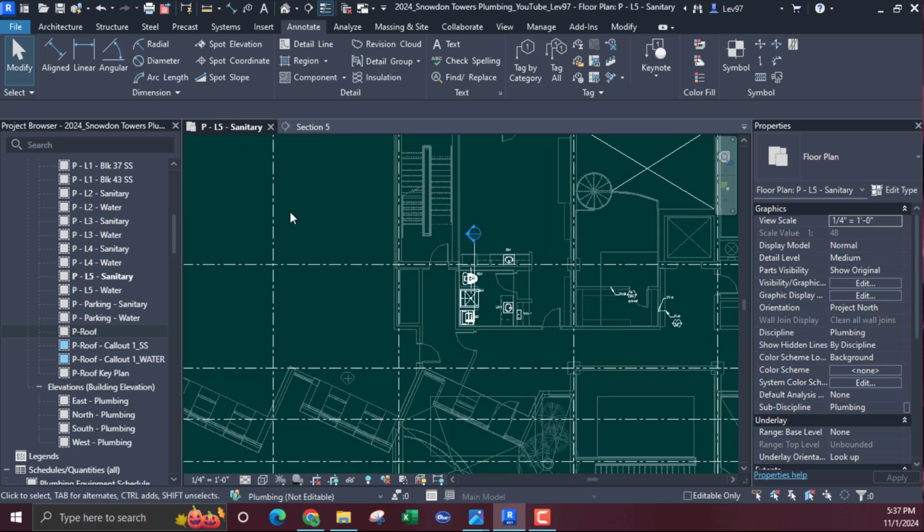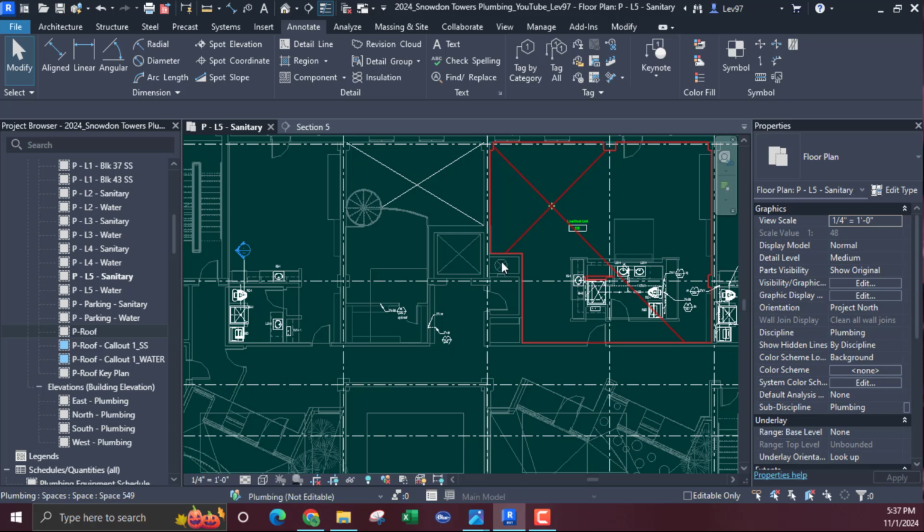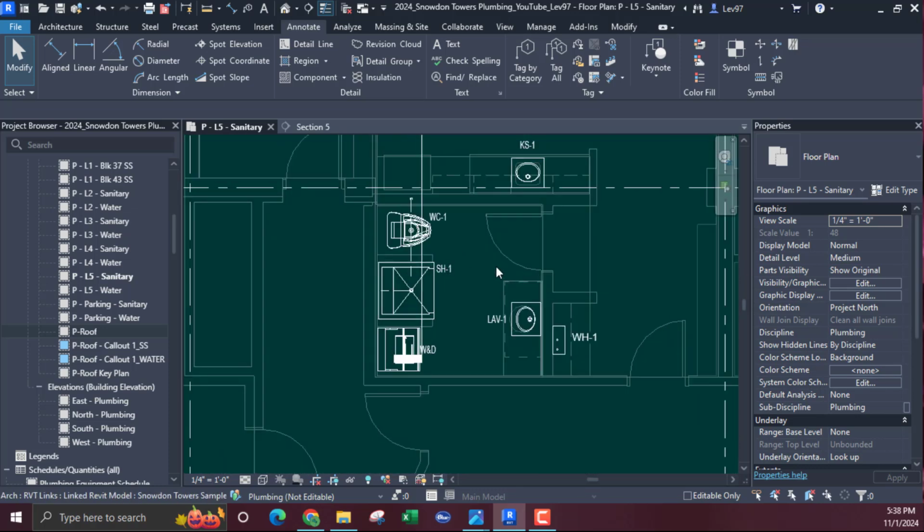Now slope would go on if I went from left to right, from here to 50 feet or 100 feet or whatever. Then I would slope it. But there's too many changes that are going to happen, and the fittings to fit slope piping are not as straightforward as the fittings that connect directly to a non-sloping pipe.